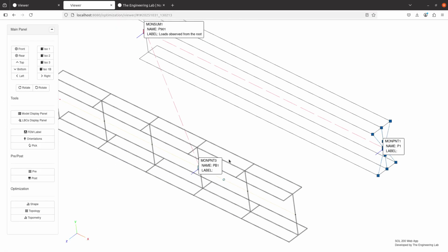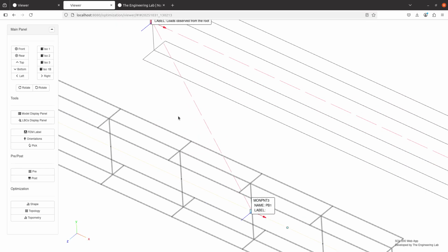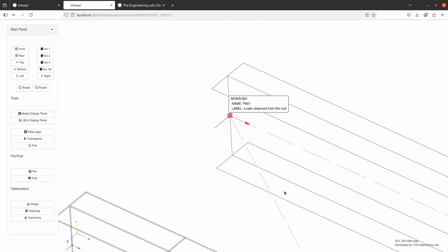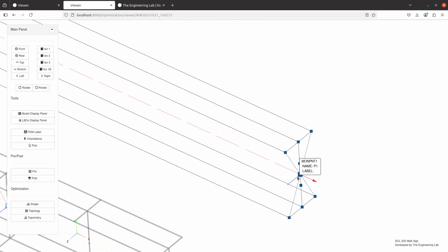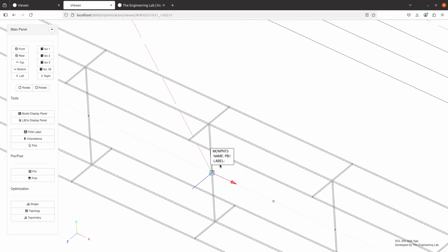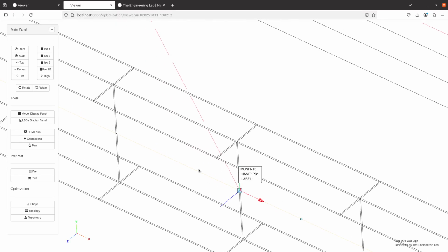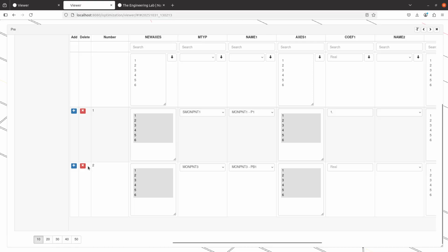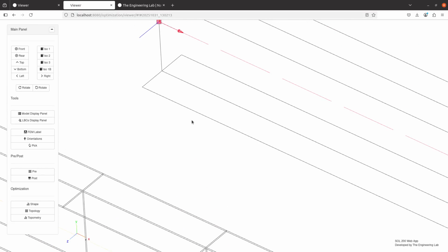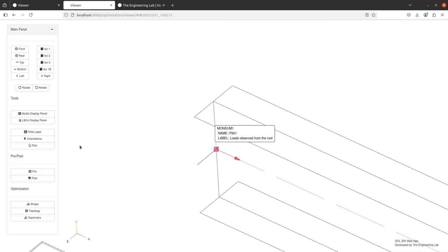Let's go ahead and see if we get an update here. Okay, so now you see we have a new dash line. So this summation monitor point is now including this monitor point and this monitor point in the summation. But here, we're not considering this monitor point, so I'm not going to consider it. I'll remove it, and then the monitor point for the summation is updated.